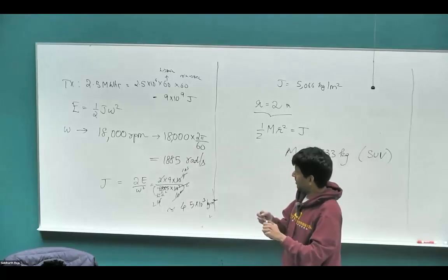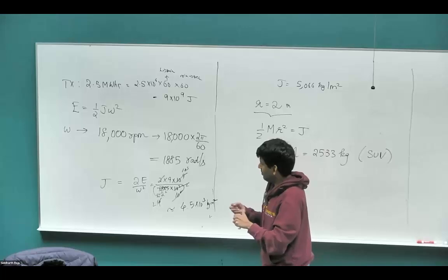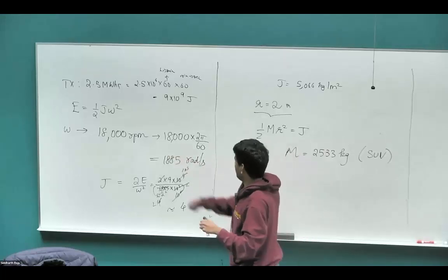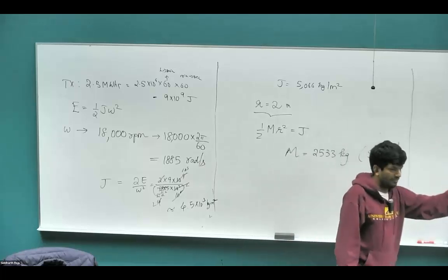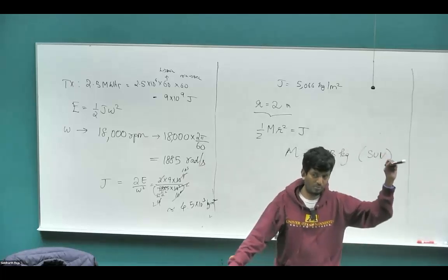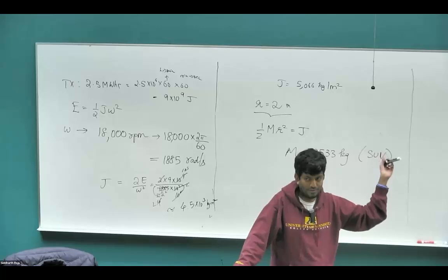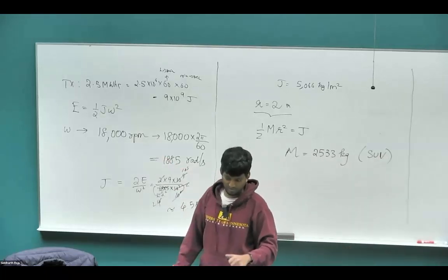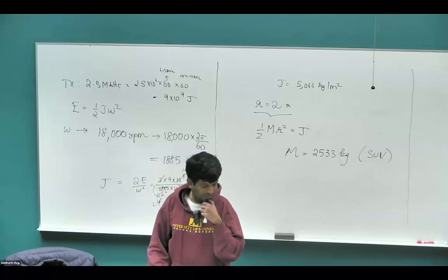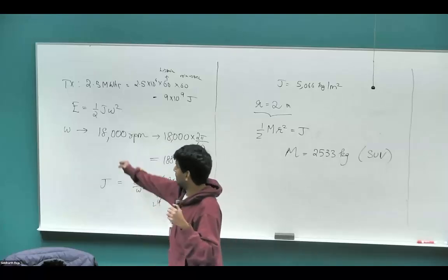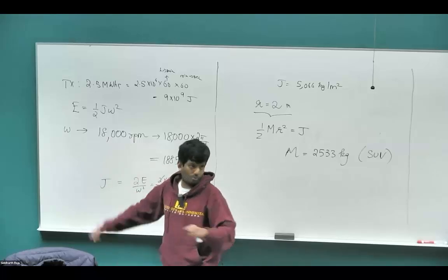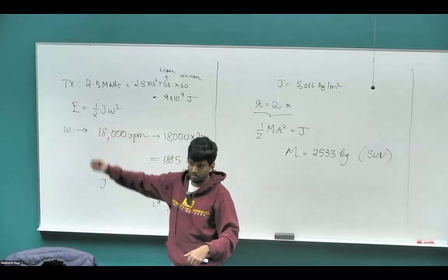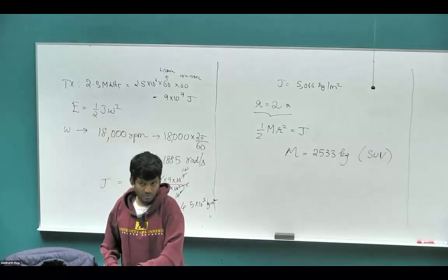And that's the reason it's not too popular, because of all the danger associated with it, and also the cost that goes into this. Reservoirs you can easily find: one at the lower level and one at the top of the hill. All you need to do is put a pump and you've got energy storage right there. But this needs to be constructed with a lot of engineering. Right, but if there is a material breakthrough and this can go to much higher speeds, this would far outpace the energy storage that you can get with a reservoir, because just by doubling speed, you get 4 times the energy storage. Right? Anybody have any questions?